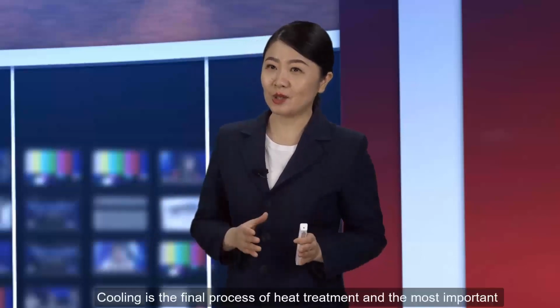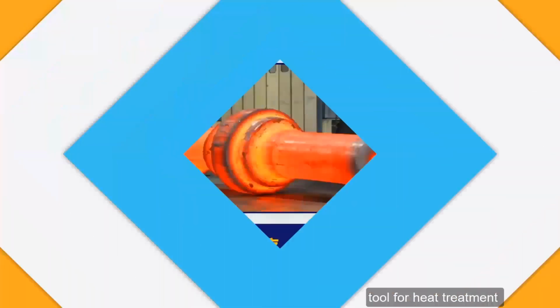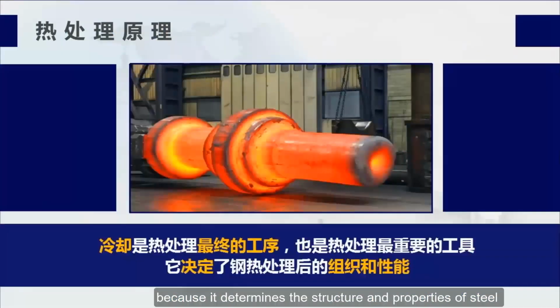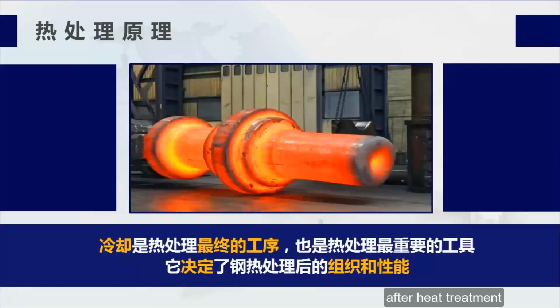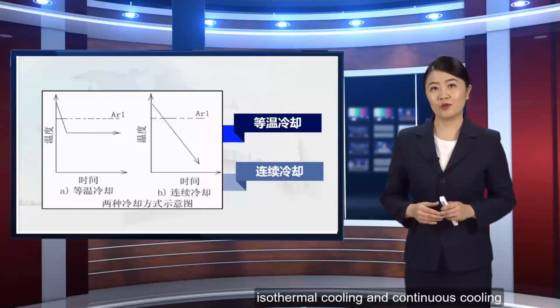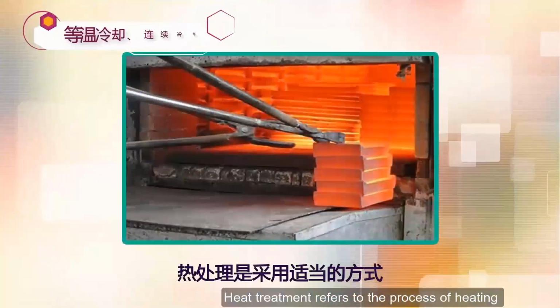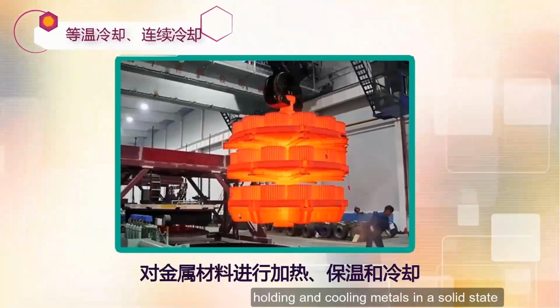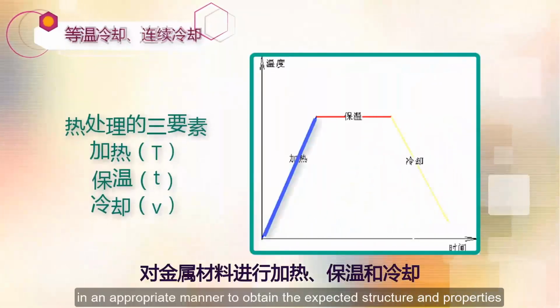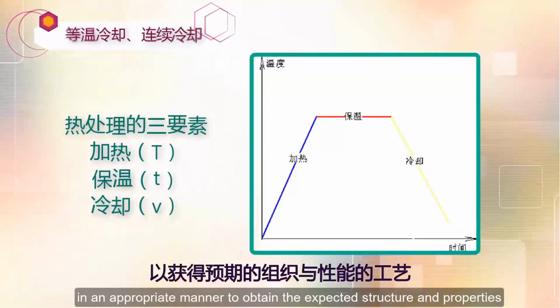Cooling is the final process of heat treatment and the most important tool for heat treatment, because it determines the structure and properties of steel after heat treatment. In heat treatment production, there are two commonly used methods: isothermal cooling and continuous cooling. Now let's take a closer look. Heat treatment refers to the process of heating, holding and cooling metals in a solid state in an appropriate manner to obtain the expected structure and properties.